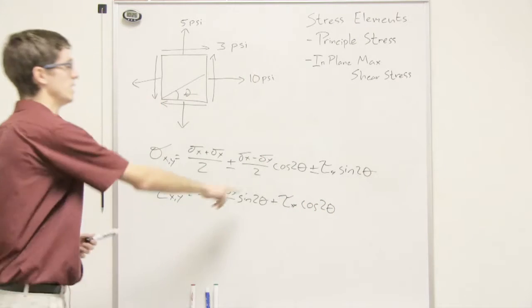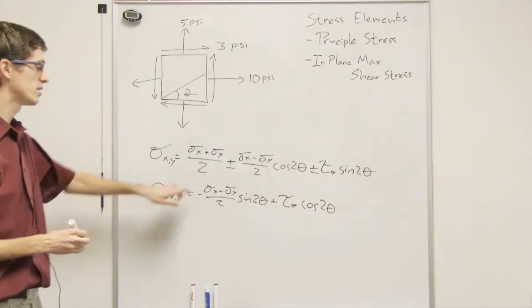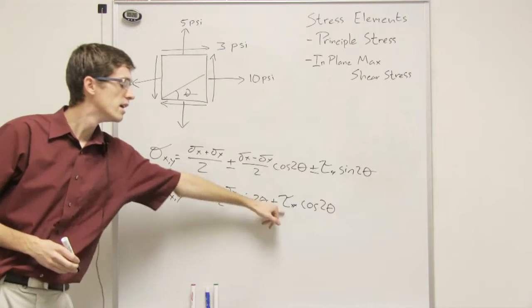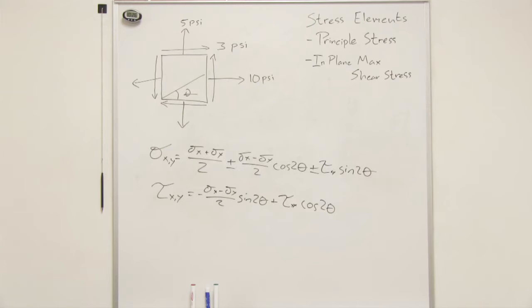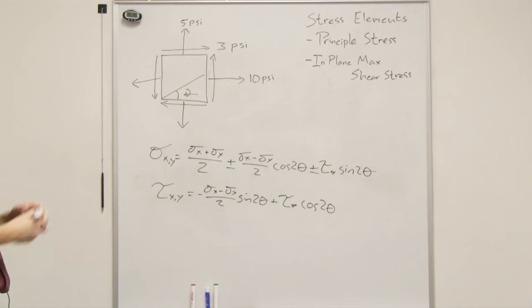It's the same thing. Theta is how much you're trying to rotate it, and then you plug in your sigma x, sigma y, and your shear right there.